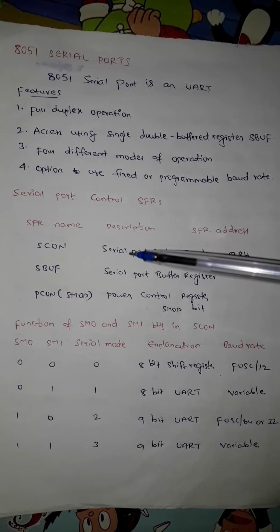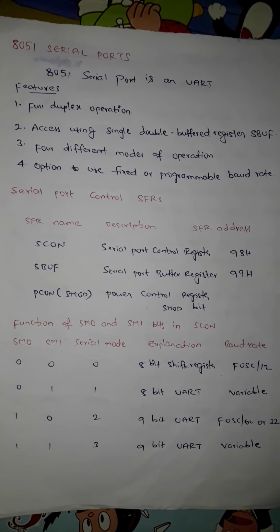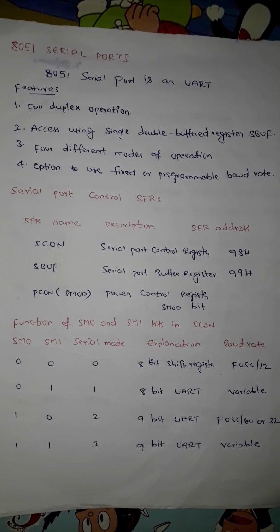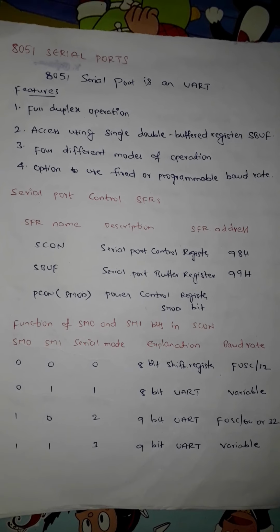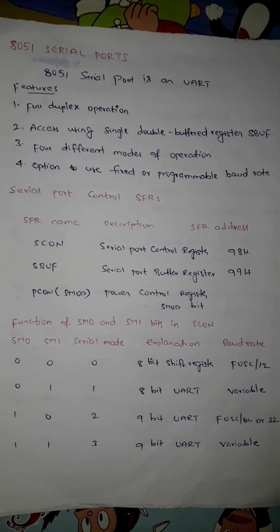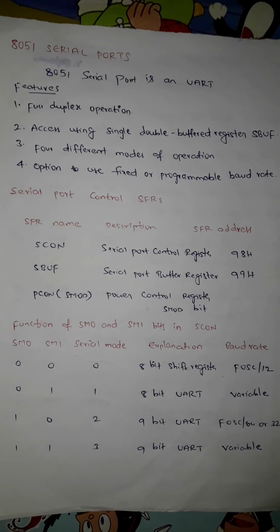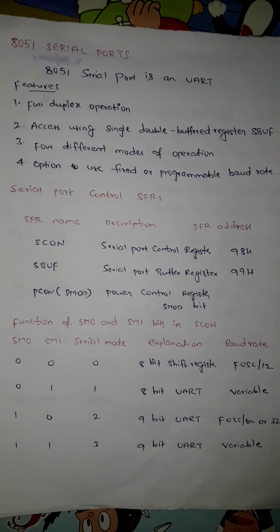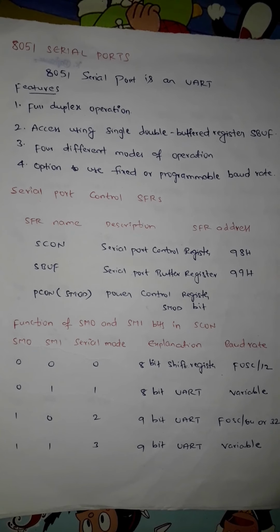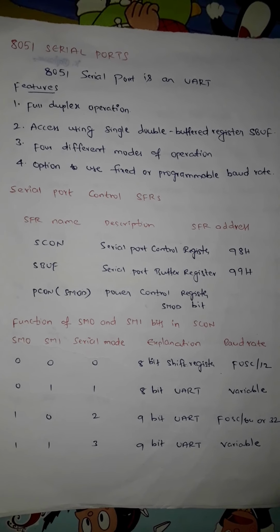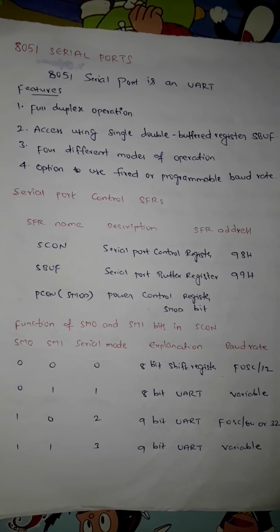And then you have the SBUF register, that is the serial port buffer register, and it is used to hold the data before transmitting, and to store the data after the data is received. So we have separate SBUF registers for transmitting and receiving. And then we have the PCON register, that is the power control register. We are not going to use all bits of the PCON, but only one bit of the PCON register is used, that is the SMOD bit.